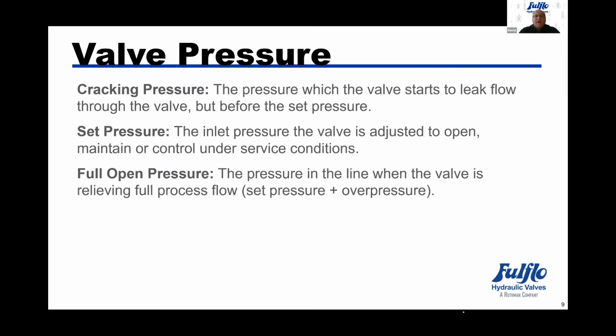Full open pressure is the pressure in the line where the valve is relieving full process flow. It's the set pressure plus the overpressure, which determines the full operating pressure at that point.